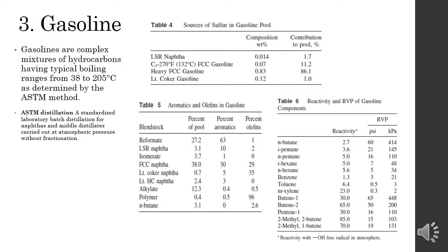Most refiners produce gasoline in 2 or 3 grades: unleaded regular, premium, and super premium, and in addition supply a regular gasoline to meet the needs of farm equipment and pre-1972 automobiles. The principal difference between the regular and premium fuels is the anti-knock performance.